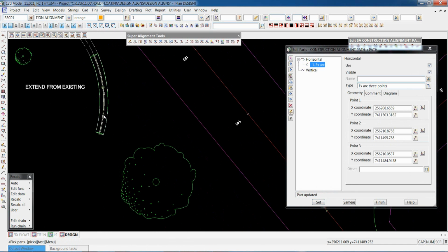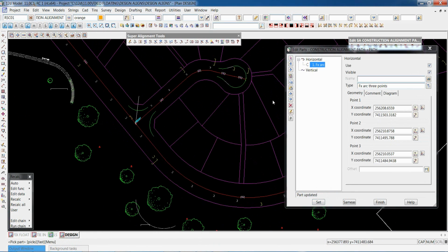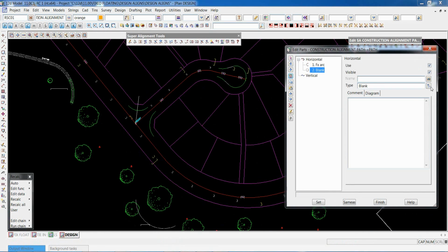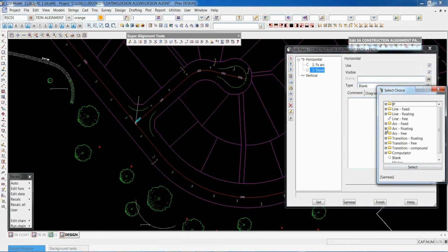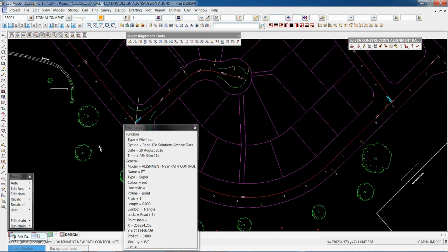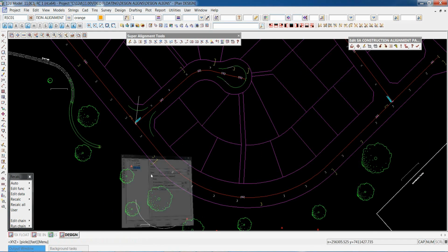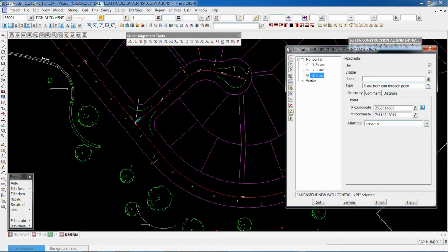So we've got the thickness of the arc. We now want to float through these known points, so it's just a matter of going insert. We go down to arc floating. We're going to do from the end of the previous part. We want to pass through a point, and the point's just that little construction point there, and it puts in the arc. So we're just going to do a few of these, so we'll copy and paste. Again, activate, pick the point, and go set.